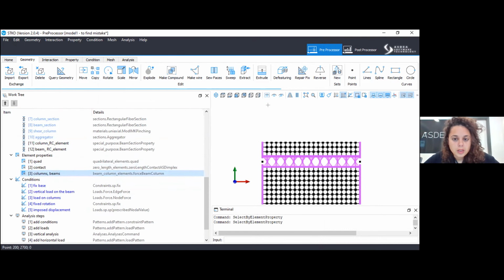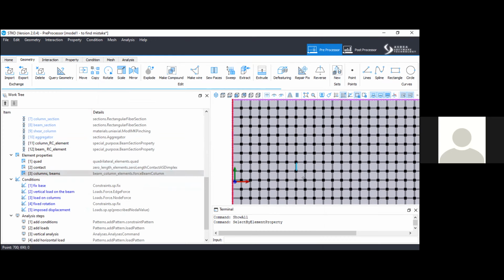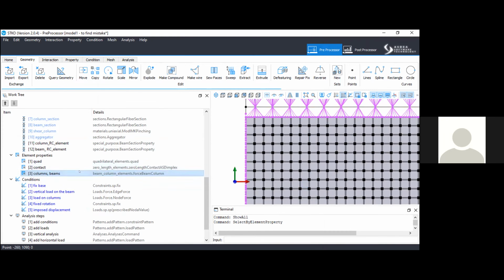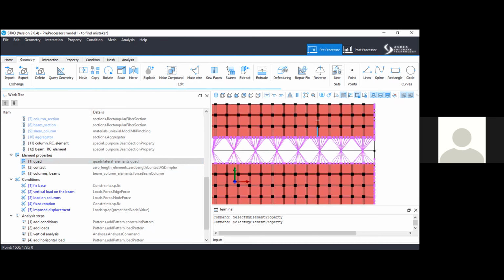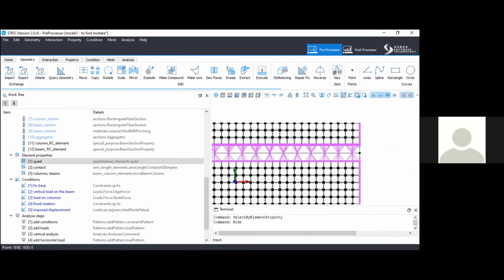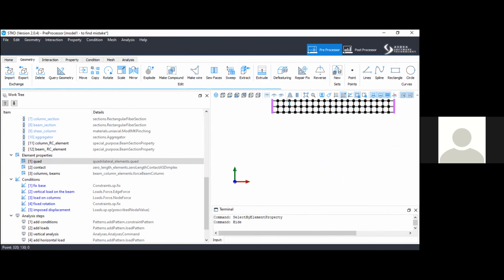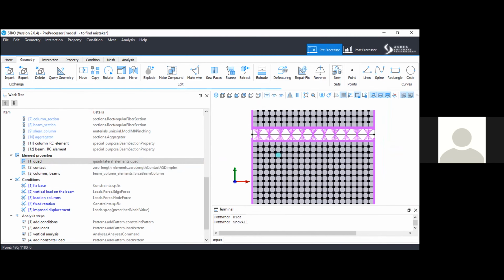Select, they are not shown. I know there's also the question of what we consider master node and what we consider slave when we do contact, from also the direction and local axis. I think it can influence the result, but it shouldn't influence that it doesn't want to run at all. I'm not completely sure that I did the contact properly regarding the local axis. Let me check it. I have another model.